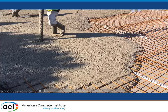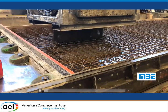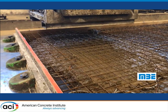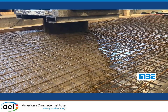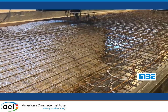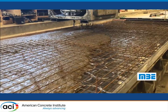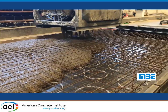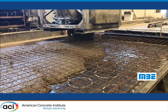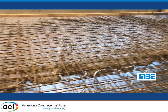Another surprise we got, and that was really a surprise because we didn't expect that the new cement would be good for precast concrete elements because of the fairly low one-day strengths. But it turned out that when the concrete element producers got the cement, they actually learned how to optimize it. Using accelerators, using a little heat, whatever. So actually, they can make good precast elements. They can also make them in an efficient manner. So today we have precast producers which are marketing, you can say, green concrete elements.